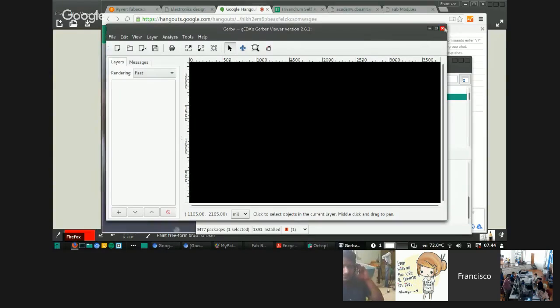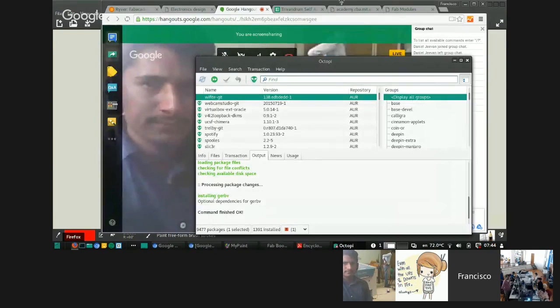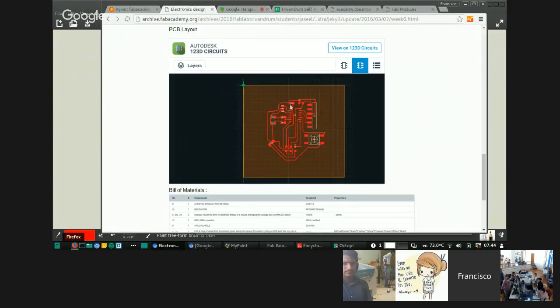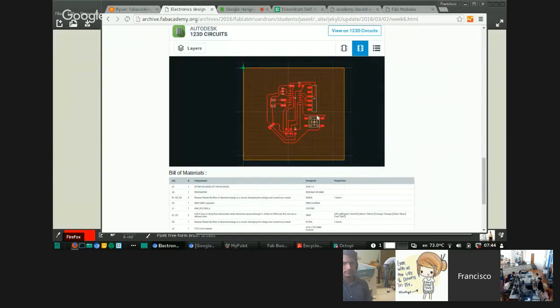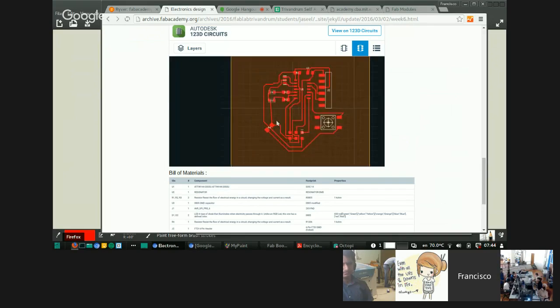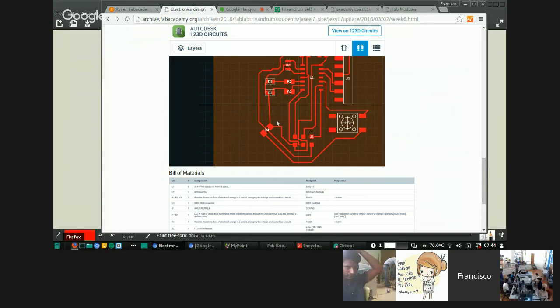Okay. So this is your workflow now. Jasil, you have to export this to Gerber and from Gerber to PNG and then fabricate the board. And start the board. Okay? Okay. So you have 1 day from now.